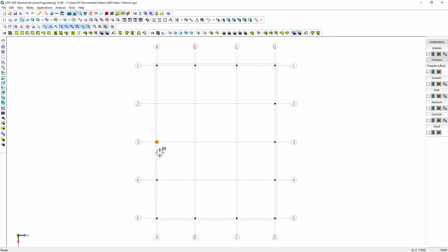You can click at the intersection on the grid, or use the box selection command by maintaining the mouse button pressed. Make sure that the created joints are only at the marked intersection of the columns and that they are not present at any of the slab's border. We will use these joints to create the columns supporting the slab.